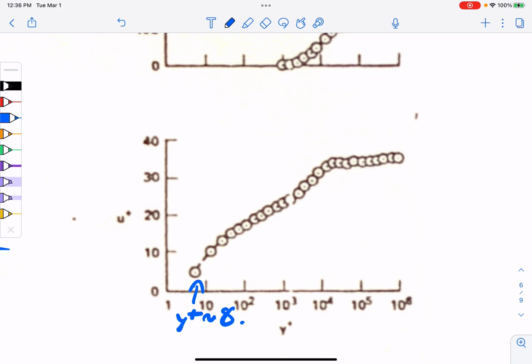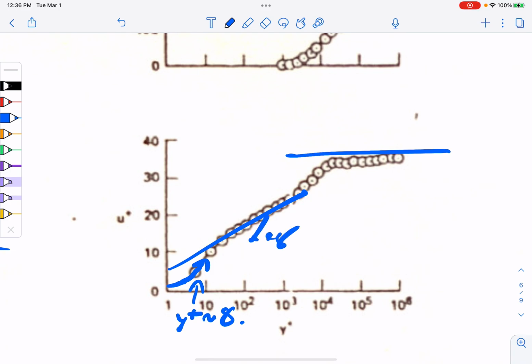And you can easily afford to get y plus less than 1 in your code if you want, but it's overkill. And then we say, okay, well, there's something like this. Here's y plus, u plus. Here's the log layer, and here's the Coles outer wake region. So this is a log layer, and this is what I call the outer, or I like to call Coles wake, because that's peer reviewed and theory where it comes from. So that looks great. That's at 80% x over c.